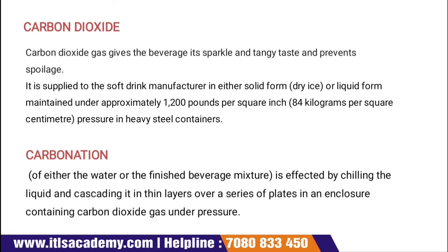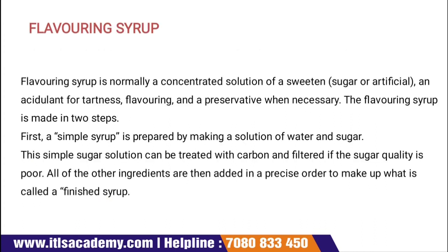Then comes the carbonation. What is carbonation? So carbonation of either water or finished beverage mixture is affected by chilling the liquid and cascading it in a thin layer over a series of plates in an enclosure containing carbon dioxide gas under pressure. So carbonation is either of water or finished beverage, affected by chilling the liquid in thin layers over a series of plates in an enclosure containing carbon dioxide gas under pressure.